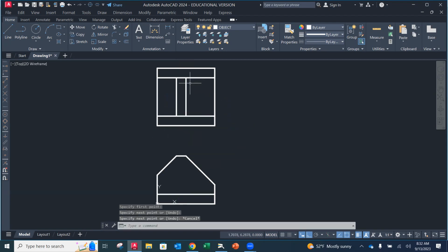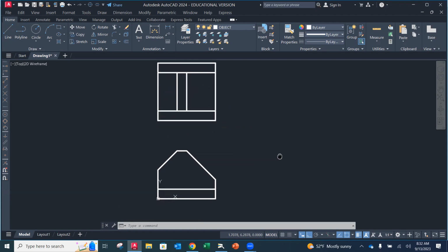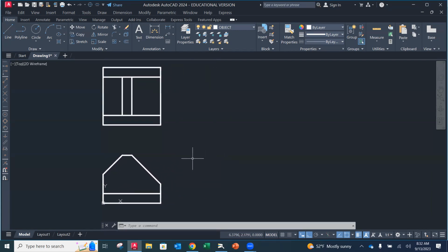Okay, so perimeter wise, we've got the top view, the front. We might as well add the right side view at this point, right? We'll add the hole. We know that the hole is coming. That's really going to be the focus of our auxiliary view. So now let's add our right side view here. I'm going to add a line. I'm going to start with the bottom here, with a little bit of distance in between. It does not have to be exactly the same unless you wanted to use the miter line method, but I'm not going to.